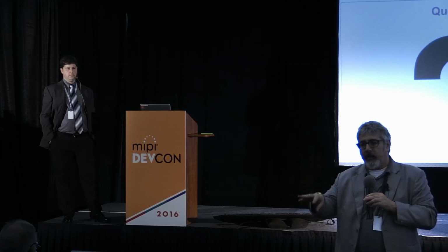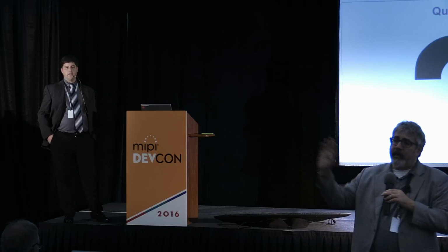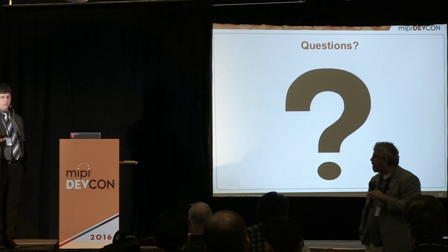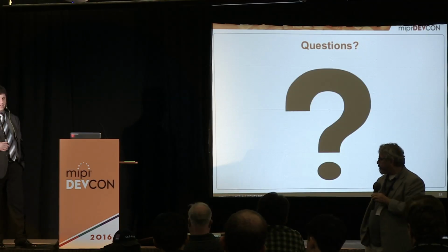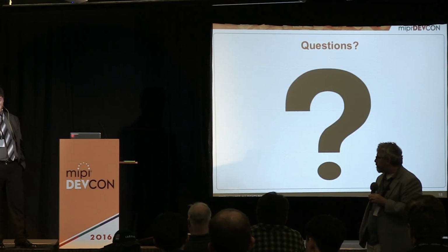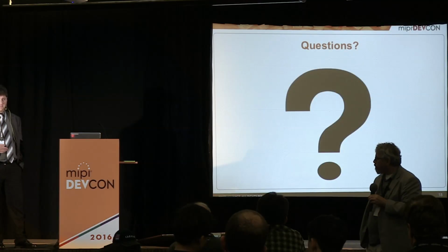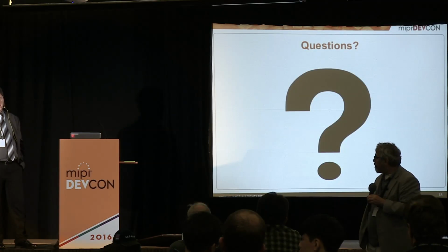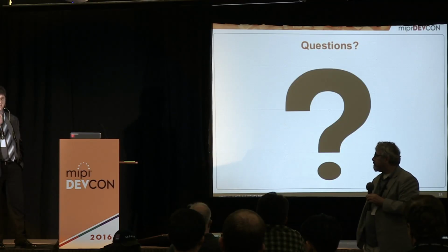If there's a particular technology, I might know whether the CTS is already available. For UFS, that's a JEDEC specification, so we don't. But the M5 and Unipol CTSs are widely used. Unipol now has CTS version 1.1 for Unipol 1.6 and 1.61, which are used by UFS. So basically, if you are going to test UFS, you also need to test M5 and Unipol. They are widely used by all the manufacturers right now and also in our interoperability events.